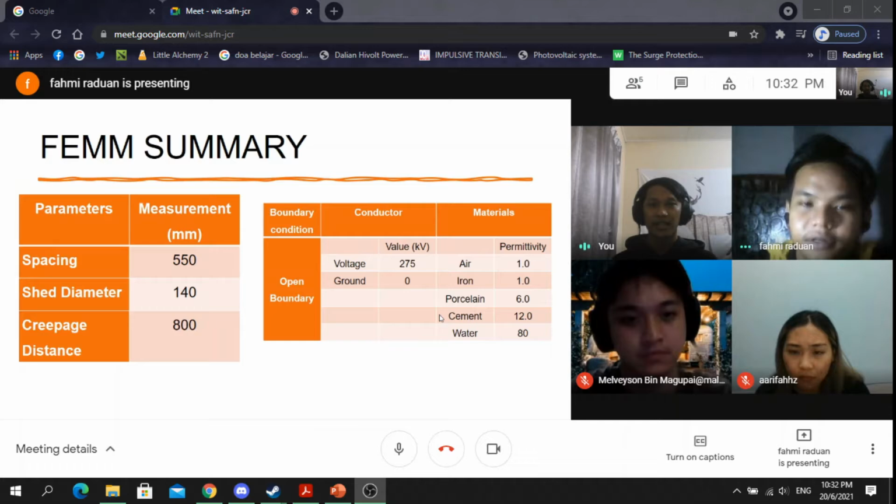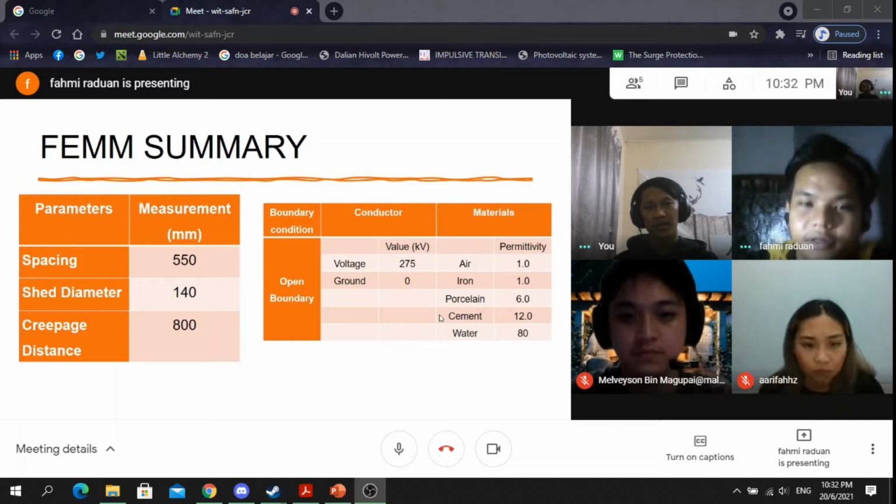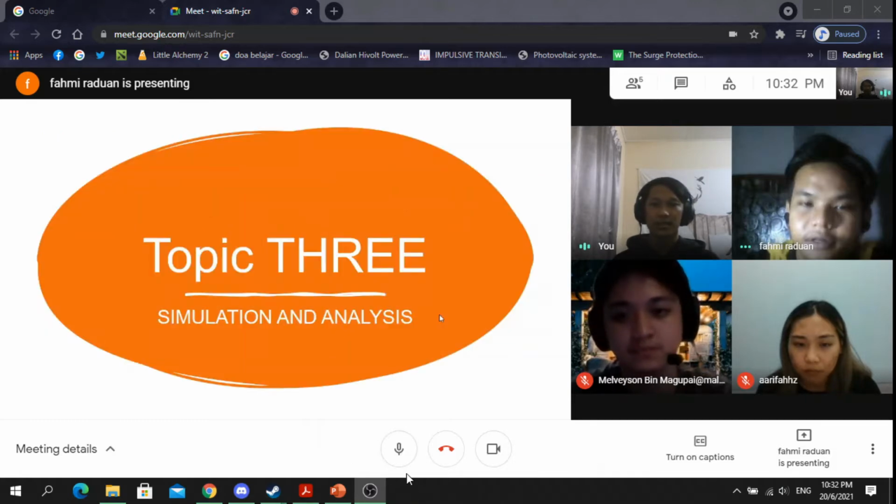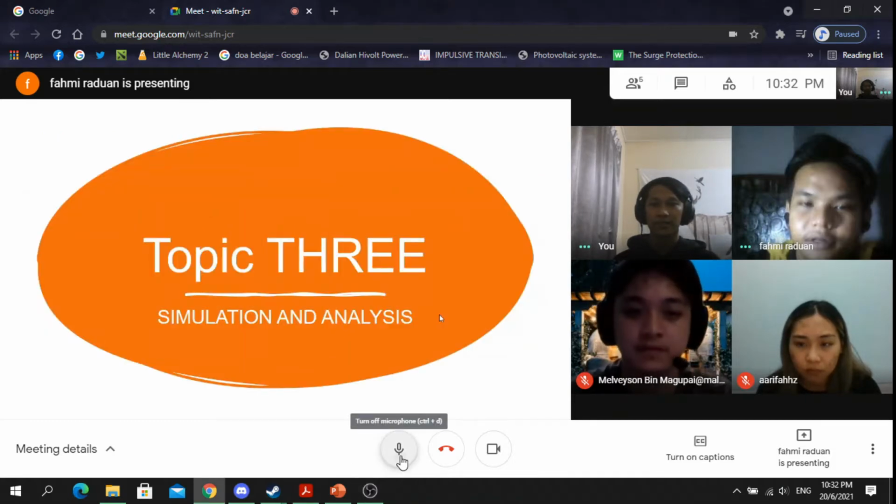The voltage in FEMM is 275 kilovolt, ground 0, and the relative permeability of air is 1, iron 1, porcelain 6, cement 12, and water 80. Next. That's all for me. Thank you.